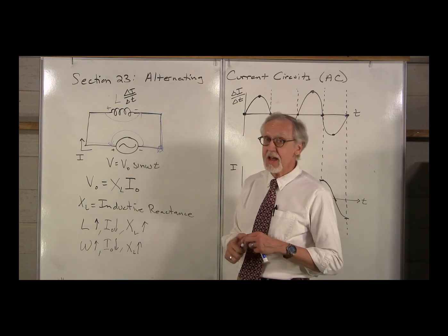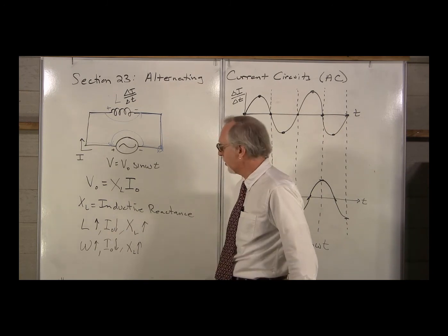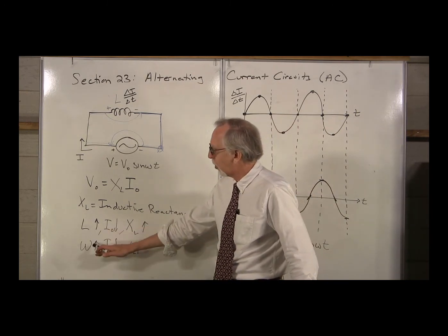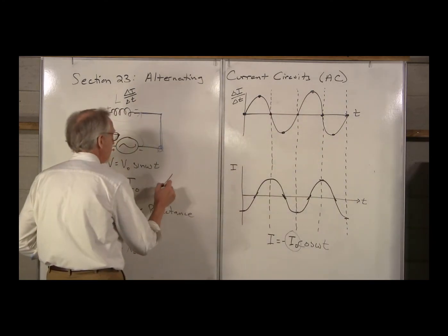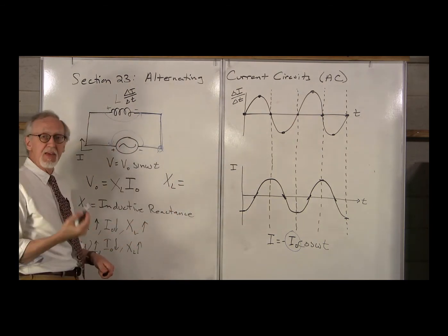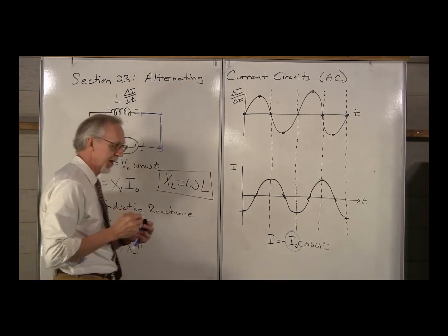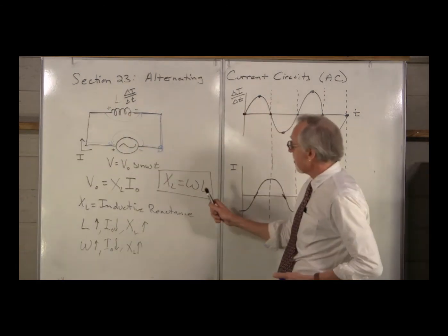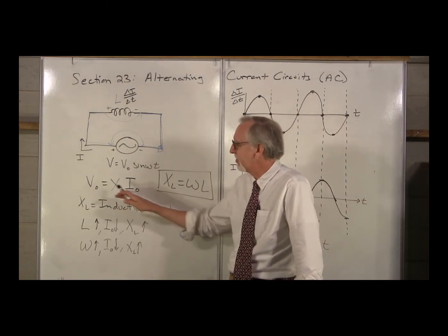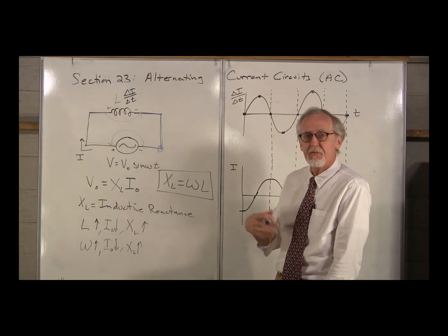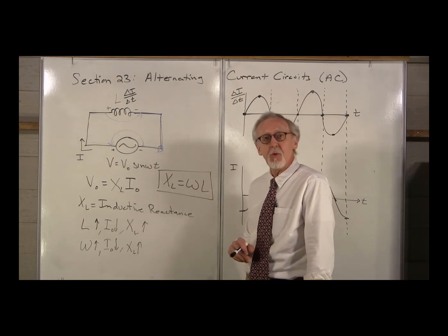Excellent. It turns out the inductive reactance does not depend on anything else other than omega and L, and we see that it must increase for increases in omega and L, and it turns out the result is then that the inductive reactance is exactly proportional to both. It is just equal to the product of omega and L. And once again, let me just mention, what are the units of X sub L, the inductive reactance? Again, same as the units of capacitive reactance and resistance, all ohms. Very, very good. Let's just recap what we found for the inductor.